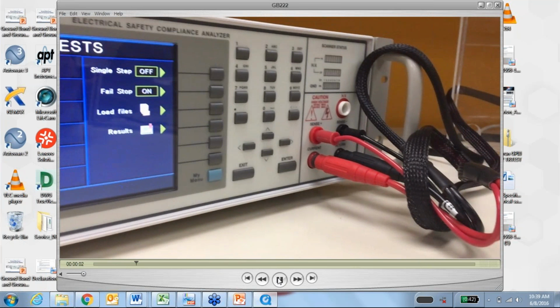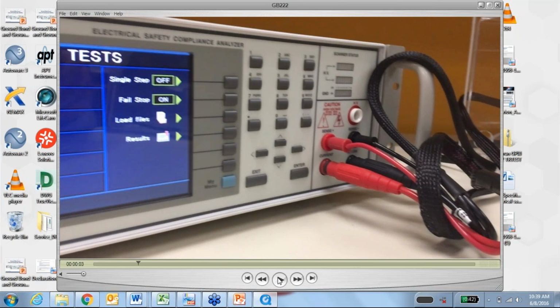testing. Okay, so here's a great shot of our 4-wire Kelvin connection that I wanted to get to. Our high current is coming out of our red lead here, going through our DUT back to the return, while our sense plus, sense minus connections are making the measurements at our connections, so you don't have to worry about creating an offset. You don't have to worry about the internal impedance of your test system or the cables. Some people can use 10-foot cables, 20-foot cables, 5-foot cables, regardless. That creates extra resistance on your test. And if you're not offsetting that, you could be getting false failures.